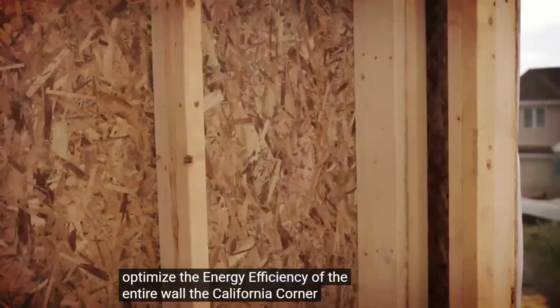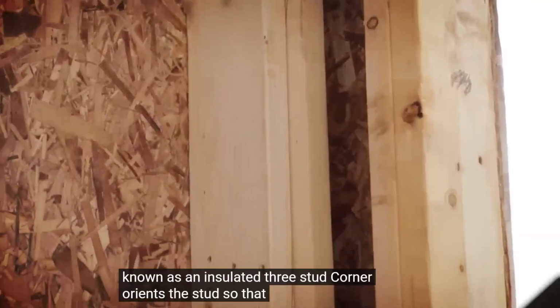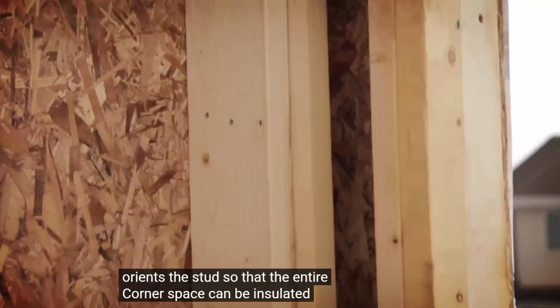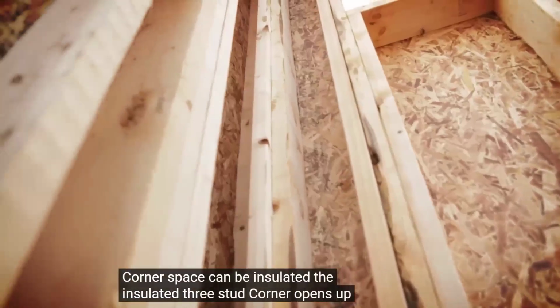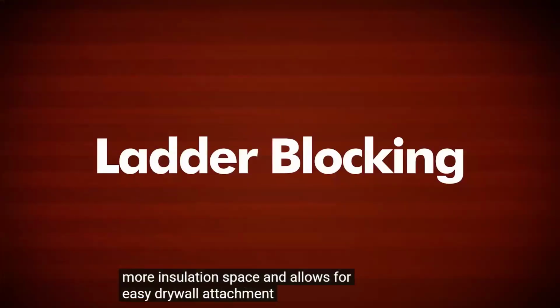A California corner, also known as an insulated 3-stud corner, orients the studs so that the entire corner space can be insulated. The insulated 3-stud corner opens up more insulation space and allows for easy drywall attachment.